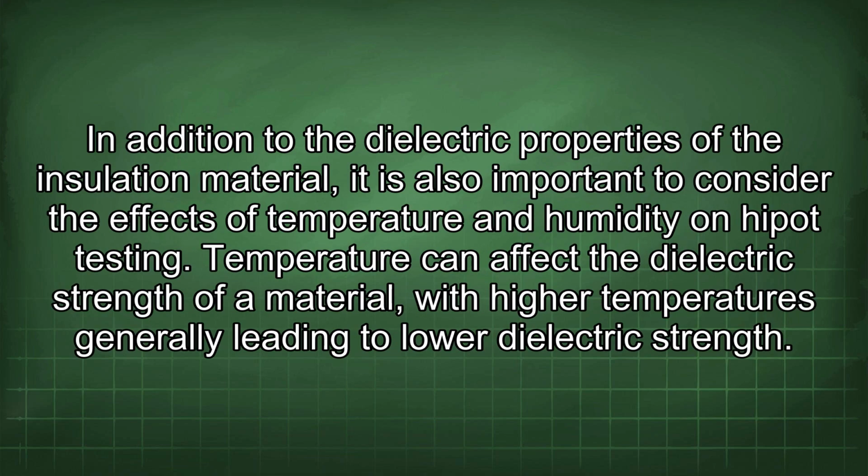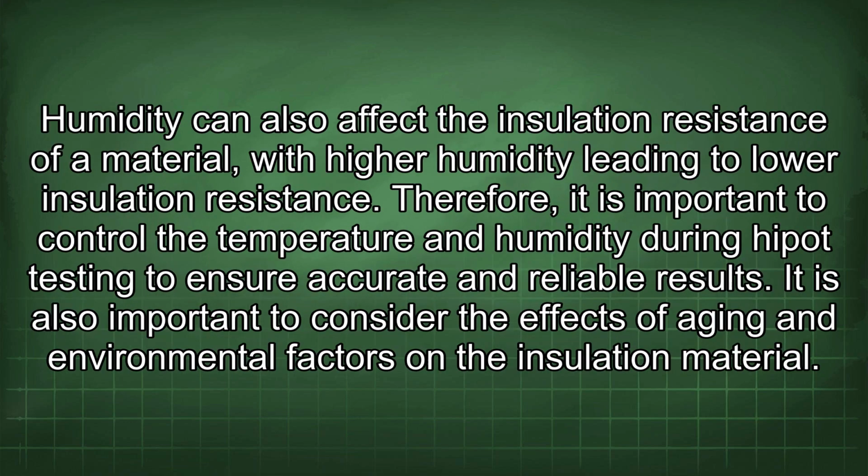In addition to the dielectric properties of the insulation material, it is also important to consider the effects of temperature and humidity on Hipot testing. Temperature can affect the dielectric strength of a material, with higher temperatures generally leading to lower dielectric strength. Humidity can also affect the insulation resistance of a material, with higher humidity leading to lower insulation resistance. Therefore, it is important to control the temperature and humidity during Hipot testing to ensure accurate and reliable results.